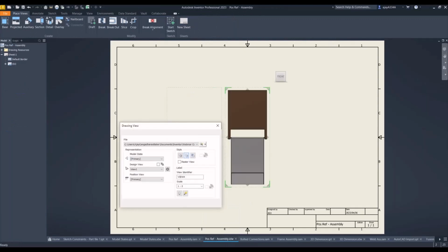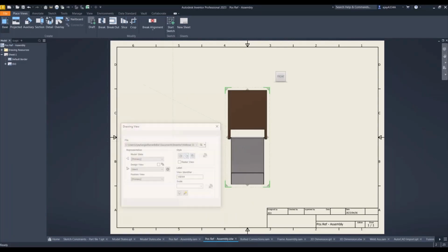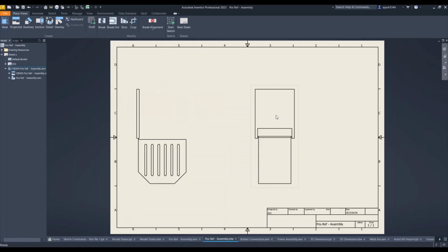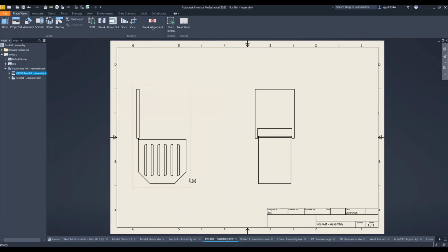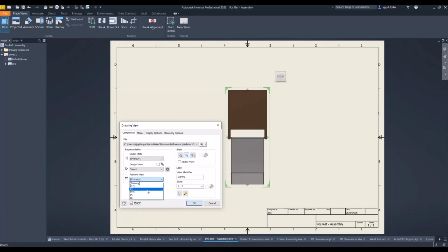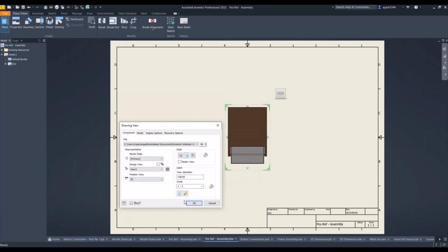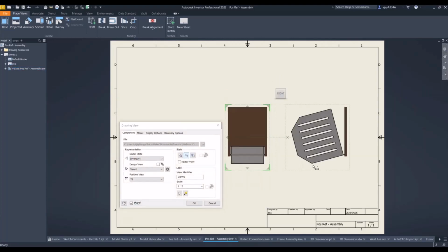And where it becomes even more interesting is when you actually do a drawing for this assembly. Let's add our positional representation. Let's put our base part there. Here, in this situation, what we've done is we've created a position view in the primary state. So you can actually do it like this as well. So let's just remove all of the views, and I'll quickly show you. If we do a base part here, you'll see that you can change the positional representation that is actually available to you. Now, you can see that that's the positional representation that's in place.